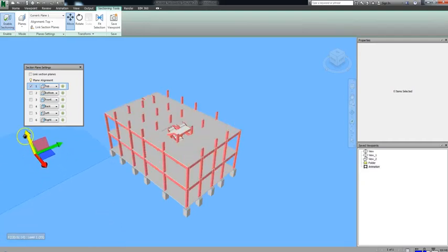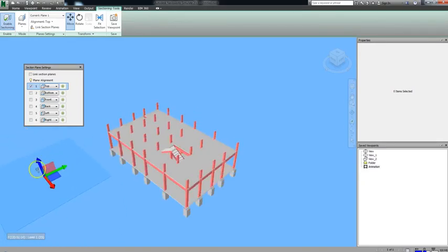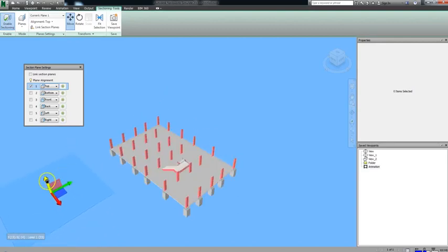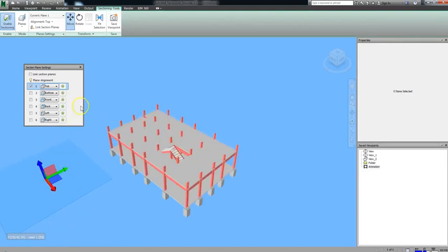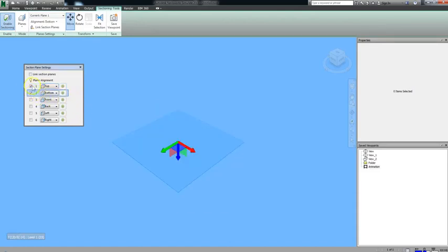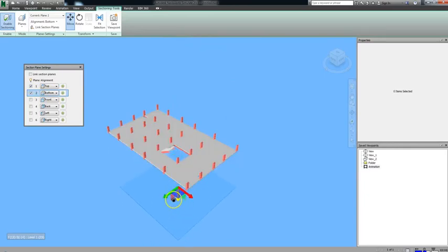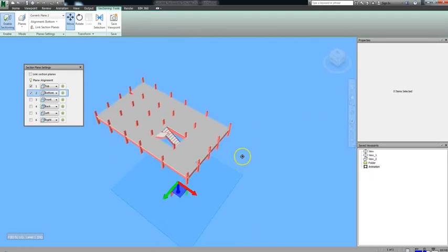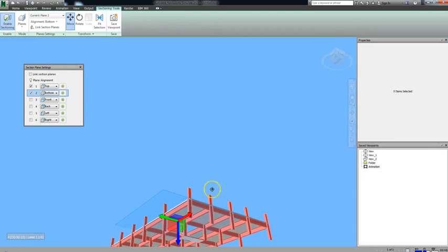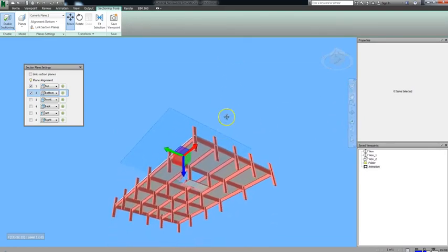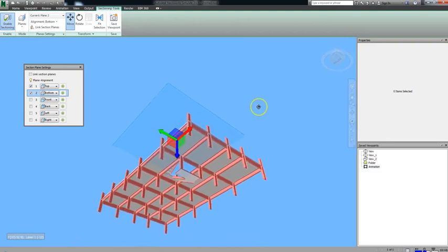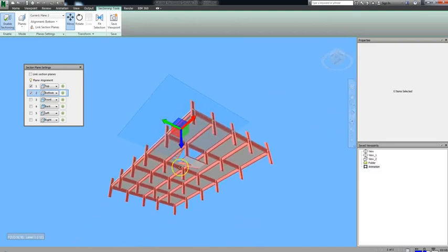The gizmo actually makes using the planar settings very intuitive, so you can play around with it and get a feel for how the sectioning works in Navisworks. Note that if you have multiple sections running at the same time, both will apply. So if we turn on the bottom section, you'll notice that we can't go any higher than the visibility of the top section that we originally created allows us. Combining sections like this can be very effective for narrowing in on one particular part of your model, especially if it's somewhere in the middle.